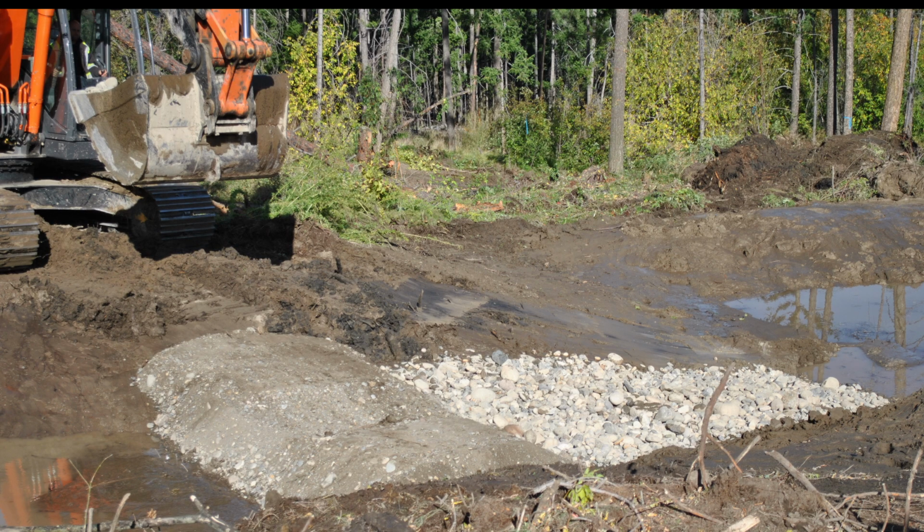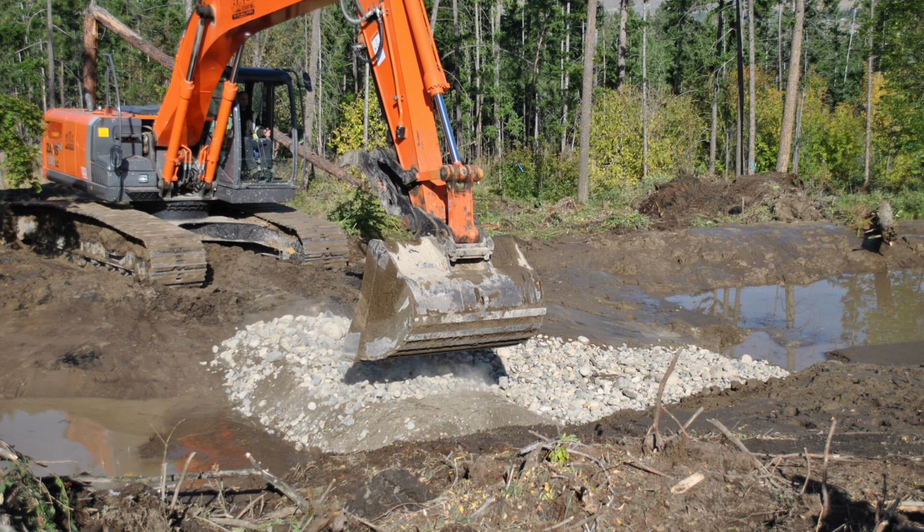Tim placed a layer of fine limestone dust from the quarry over the top of the groundwater dam to serve as a base for the rock. The fine limestone will harden like a well-traveled gravel road. He now spreads rock over the surface of the groundwater dam. This is so it won't erode. The elevation of the groundwater dam will be the same as the original surface of the ground before the wetland was built.